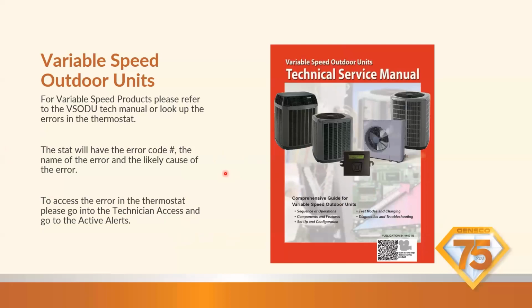Now, if you just go to the thermostat where it has the error code flashing across the top and you just press and hold there to look at it, you're going to see the homeowner facing error code. It doesn't give you the details. It doesn't give you everything. You really need to get into the technician access and go to the active alerts, or even alert history, but the active alerts are going to tell you what's actually going on. And you can touch each error code and it'll show you exactly what the likely causes are.